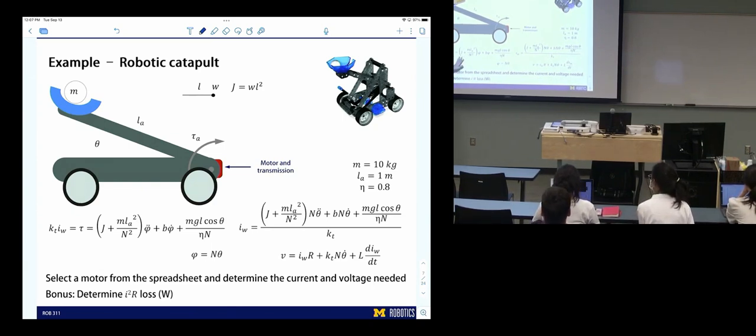There will always be an inertial component, because you're always accelerating some mass. If we're talking about motors, there'll generally be a viscous loss component. And in general, there should be a modeled loss component, which typically exists in mechanical systems. Then there's the gravitational component. This one is the only one that requires a little more mechanical engineering knowledge. We had to decide how to model it as a function of theta. But I think it's just force times distance. I'm hoping that's not too ME-centric.